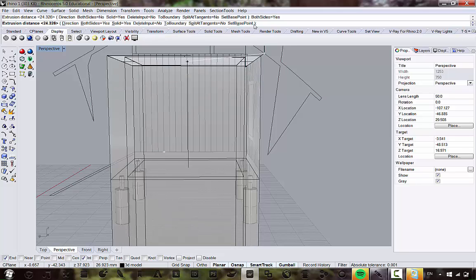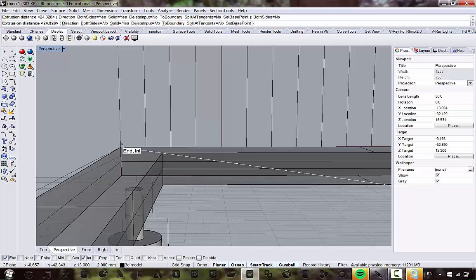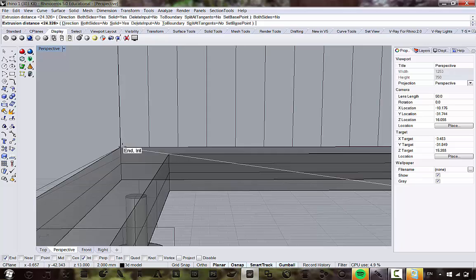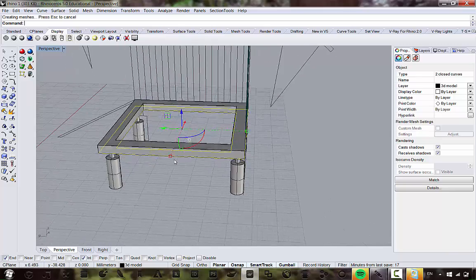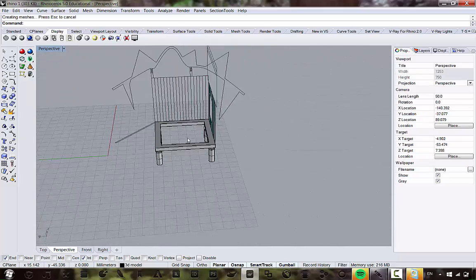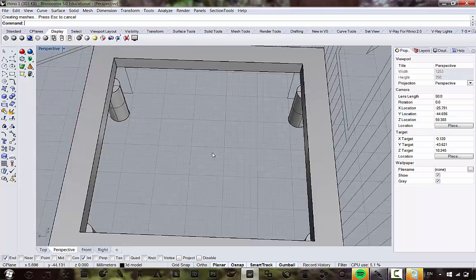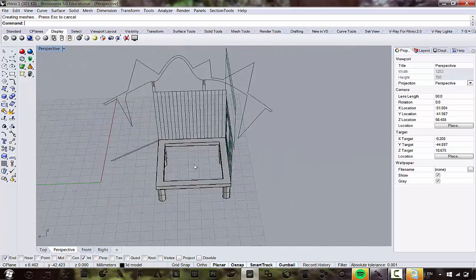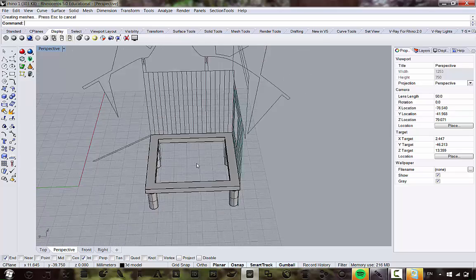So just play around with this. Set Base Points, another useful one. Just play around with that and see how it works for you. You can drag it up to a certain point, so in this case, the end point here. I'll drag it up to this point and click to end the command. And now what we have is this first extruded shape here. That's the beginning of our structure. And from here, especially on the inside, we're going to start working a little less from the drawing and more just within here, because we don't see this intersection on any of our drawings.